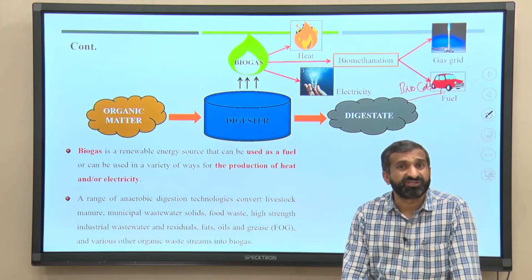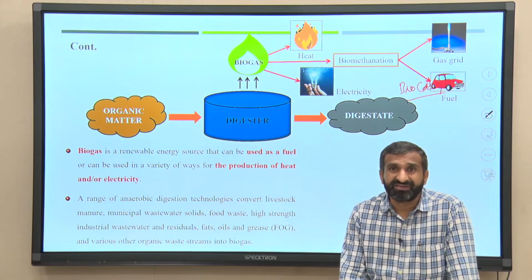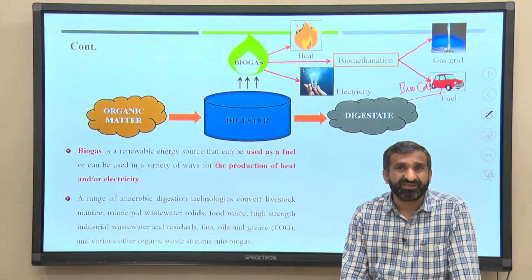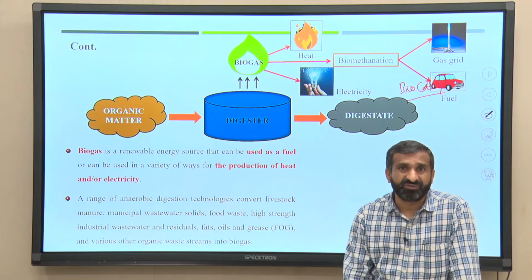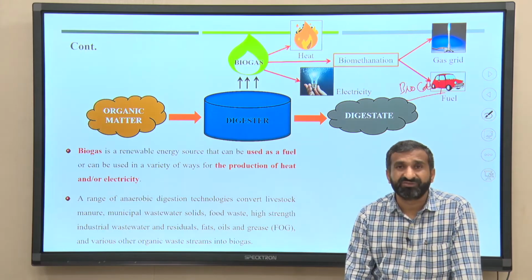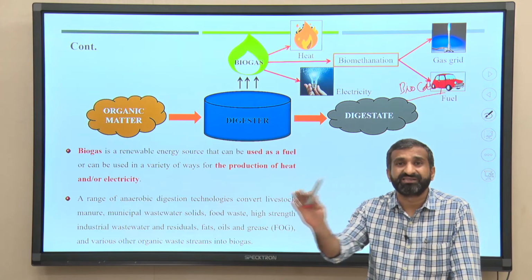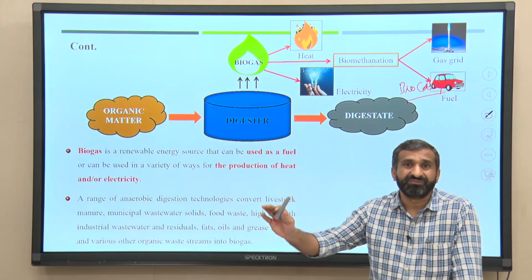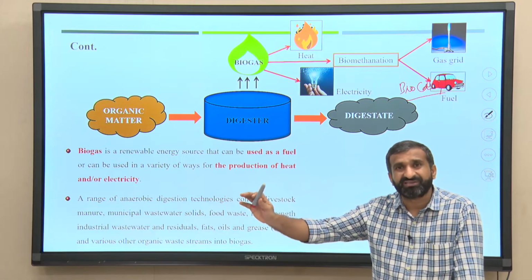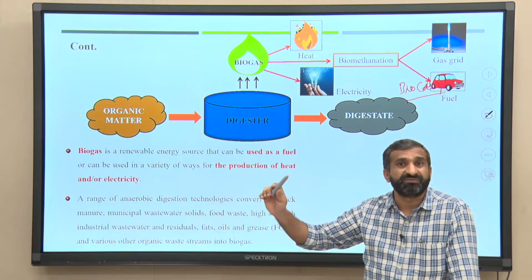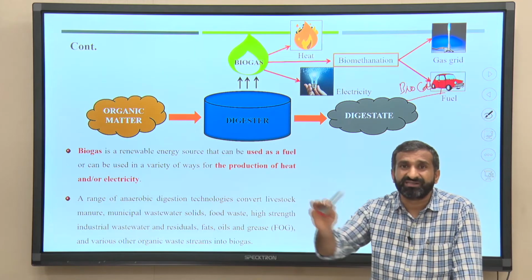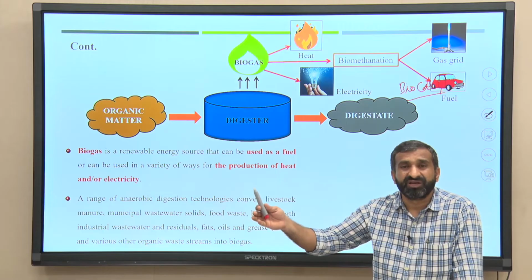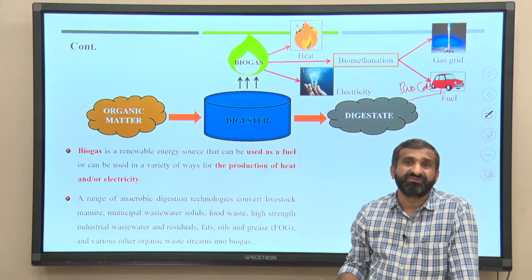Because sludge production is very low in the anaerobic digestion process. Like in the composting process, where glucose degradation to compost or final sludge goes up to 30%, in the anaerobic condition the sludge produced is only 5%.